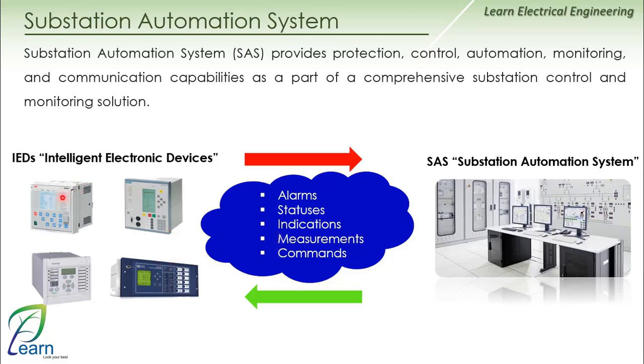I can also, through the BCU or the control unit, perform control, meaning I can give a set of commands. Great, very nice. So I placed the IED in each panel and started to take all the alarms and statuses from it. This way, I can draw a single line diagram on the screen of each of these relays or IEDs, and I can start to see my single line diagram. I can perform control, take current and voltage readings, get indication status, or receive alarms. Everything I did in the control panel, I can now do here in the relay.